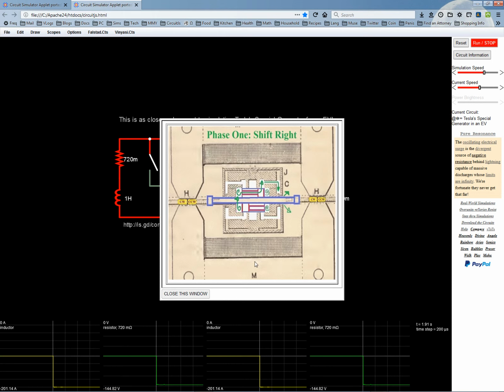And the reason why I think, let's just take this one for example, the M coils. Here we have a magnetic circuit that's kind of circular in a sense. Even though it's broken in the middle, it's still somewhat circular when the H coils are not interrupting the magnetic flow. When they're in here, they're interrupting it, but when they start to slide out, they don't interrupt it. And so right now, it's circulating all the way around. So it's a total toroidal situation. But now it's not. It's two halves. So we've got a situation in which we charge up magnetically and then we discharge the magnetism.